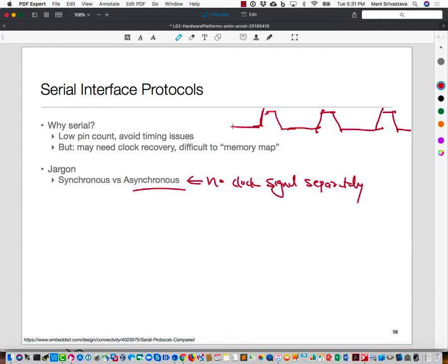Okay. While developing the initial stages of the serial interface, did they face any issues synchronizing? So I think firstly one reason to not send a separate clock is you save one line also. Besides the fact that you don't run into synchronization issues. So clock recovery, which basically means that just looking at the data, can I learn what the frequency was? Which you can, right? By examining when the data transition was taking place, you can do it. So those things went out.